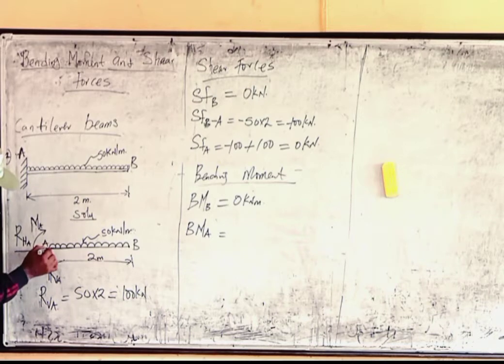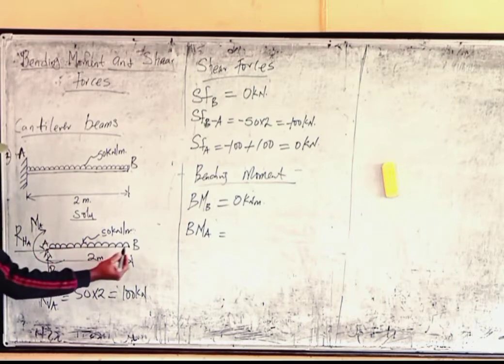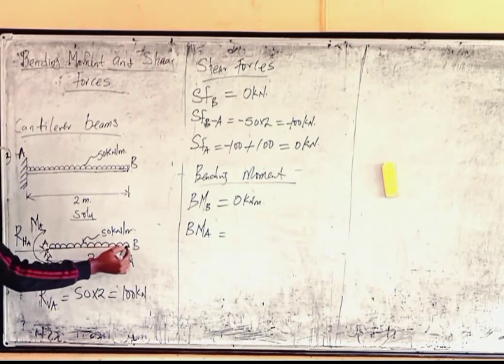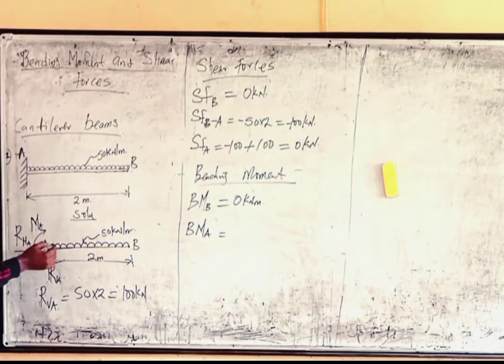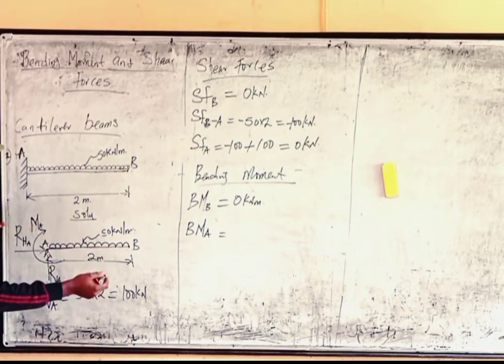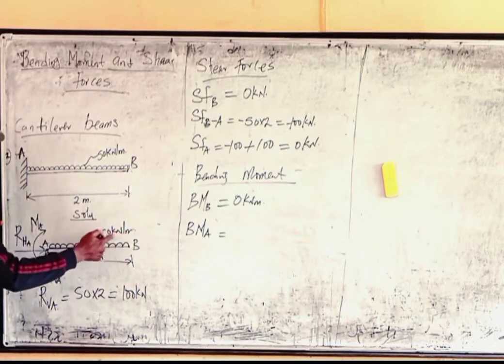I want to calculate the bending moment at this point. So what is the distance between? We don't even know where the load is. The load starts from this place, and the load is still here. You can see the load is even still here. So we don't actually know the distance to multiply the load with. That is the first problem we have, because the load is everywhere. We want to say force times distance, and this load is not a force.